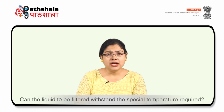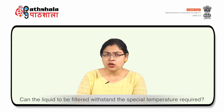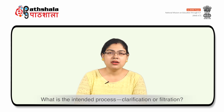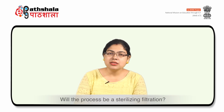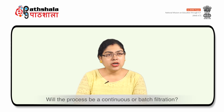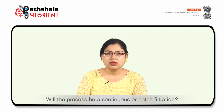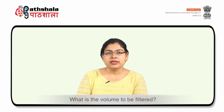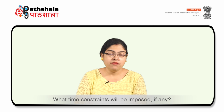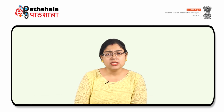Can the liquid to be filtered withstand the temperature required? What is the intended process, clarification or filtration? Will the process be a sterilizing filtration? Will the process be a continuous or a batch filtration? What is the volume to be filtered? And lastly, what time constraint will be imposed, if any? So, considering all these questions will help you in selecting filtration media and equipment accordingly.